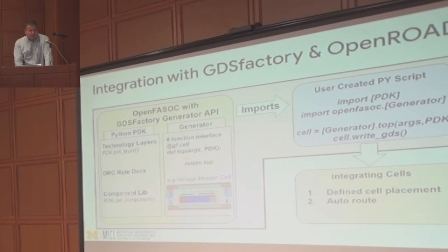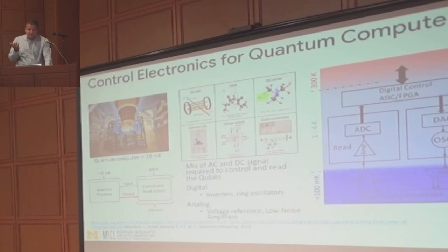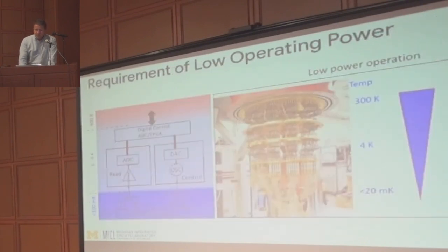With varying design parameters here, we are automatically generating a current window with various stages, shown here. So this is very cool because we can make these LNAs for cryogenic temperature design or CMOS. This is another project with NIST. One of the main applications for cryo-CMOS is to build the control system to interface with quantum processors. And to do so, the control needs to sit at around 1 to 4 kelvins.